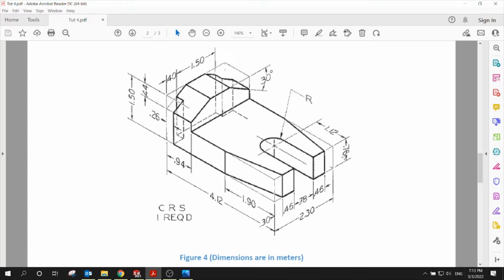of 0.76. Once I'm done with that, I'll go from that back view and then I'll create a rectangle with dimensions. Total dimension is given to be 2.3 and height total is given to be 1.5, and then I can cut out the two corners. Or I can go to the top view and make a rectangle with two small cuts and then extrude up, and finally I can cut out the chamfers. So it's up to you.